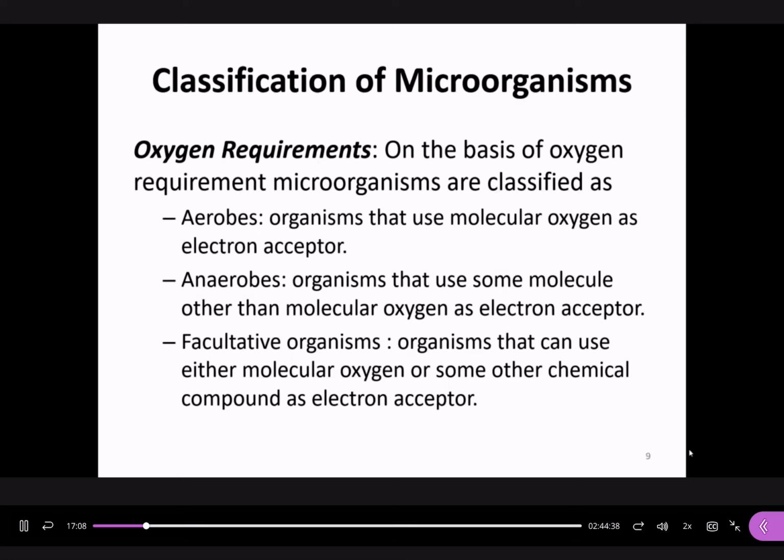So aerobic organisms utilize molecular oxygen as electron acceptors. This is what we utilize in biological wastewater treatment to remove COD. Anaerobic organisms utilize molecules other than molecular oxygen. In our coming lecture, we'll discuss this in anaerobic treatment, but we'll first talk about aerobic treatment with oxygen.